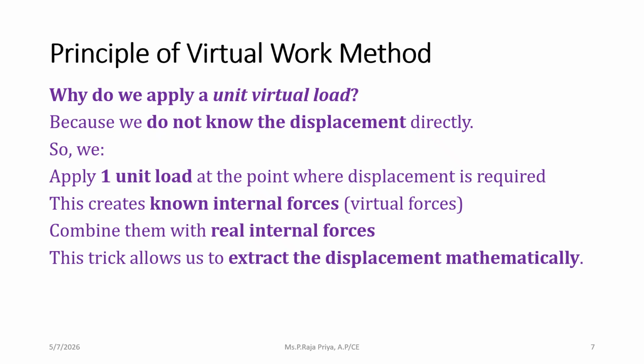This will create some internal forces, that is virtual forces, because we are applying just a unit load. These virtual forces should be combined with the real forces. Using this trick, we determine the displacement mathematically. Using that load, we combine it with the real force which is actually acting there, and using this we find out the displacement.